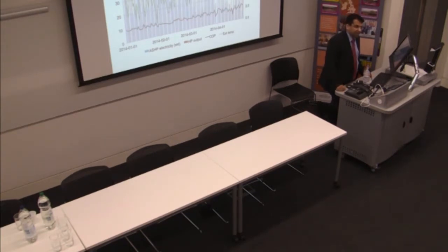More or less, the coefficient of performance was just around 2, so it's doing reasonably okay. One of the things to be careful of with heat pumps is if the temperature outside goes down really low, the coefficient of performance goes down. The more the difference between sink and source increases, the less efficient air source heat pumps become. So we've got some data there.